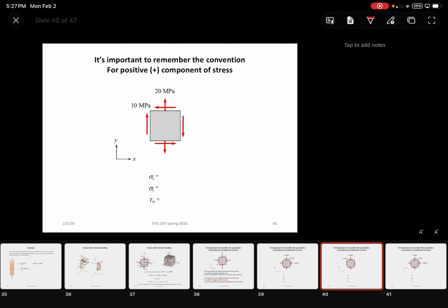Let's do this one now. I'm going to say tau xy. Let's make the magnitude for this one 30 MPa. It's missing. Who here's got it? What's sigma x? Oh, wait. Whoops, my bad. I'm orienting wrong. It's already written out. I'm looking at it wrong. What's sigma x? Yeah, 0. Yeah, confused me too, the arrows.